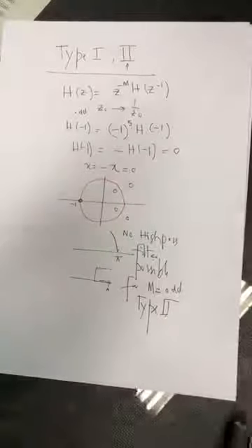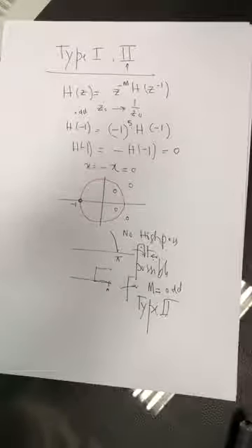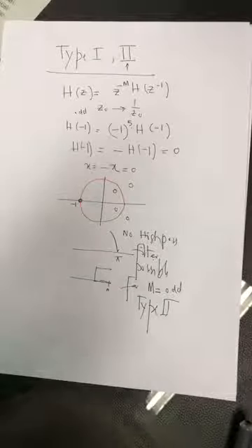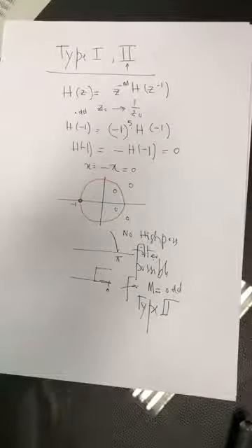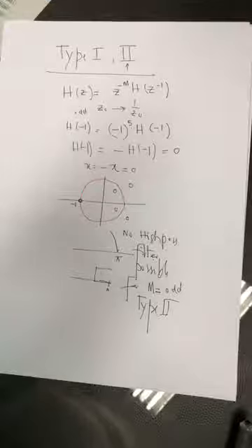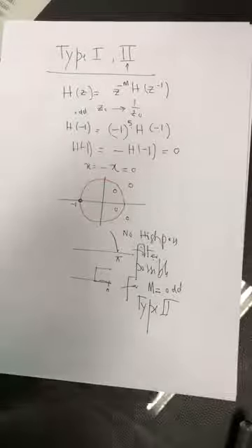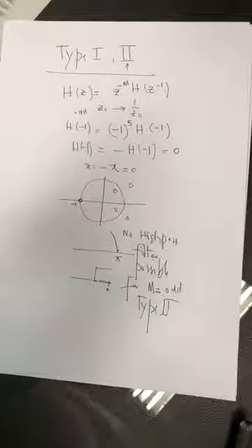So this is a very important relationship, and that's why there are 4 different types. I'll show you in a while on MATLAB. Once you design an FIR filter in MATLAB, and you say automatically select the length of the filter, just minimum length, whatever it is. So if it is a high pass filter, MATLAB will never select an M which is odd, because you cannot have a high pass filter once M is odd. Okay, so M got to be even. If you force MATLAB, I don't know, will it disobey or do something?